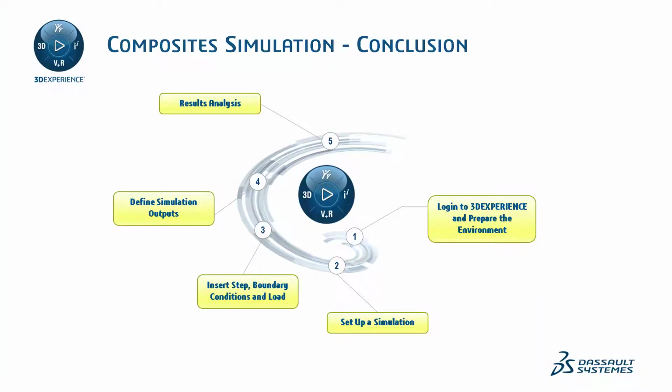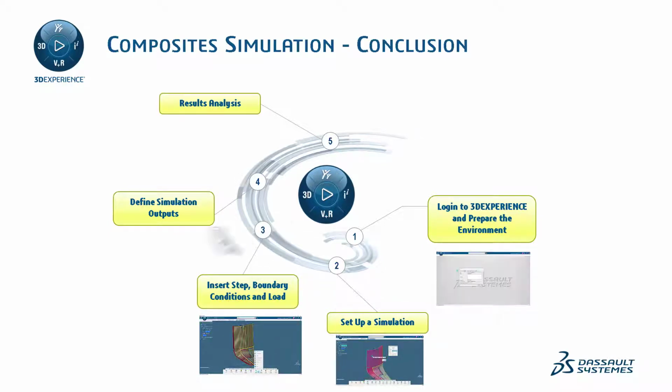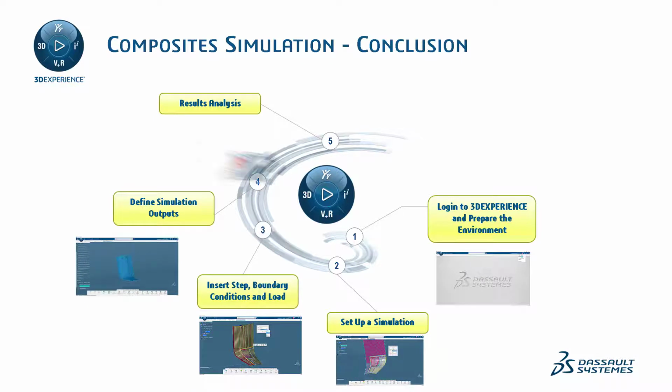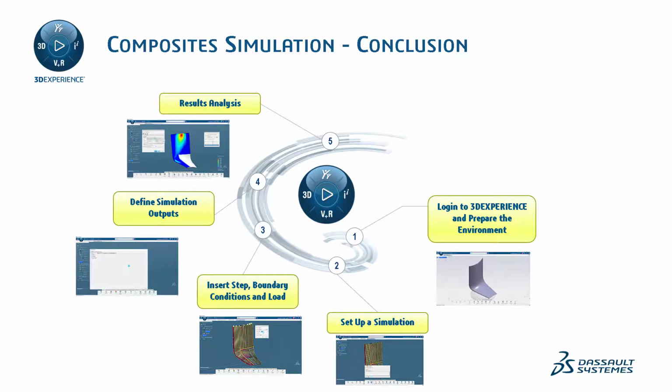This is the end of the tutorial. In this video, you learned how to log into 3DEXPERIENCE and prepare the environment, set up a simulation, insert step, boundary conditions and load, define simulation outputs, and finally, perform a results analysis. Don't hesitate to watch this tutorial again, and reproduce all the steps by pausing the video.